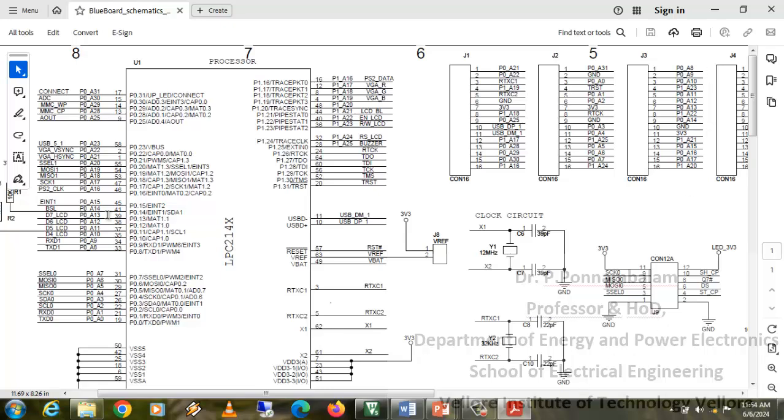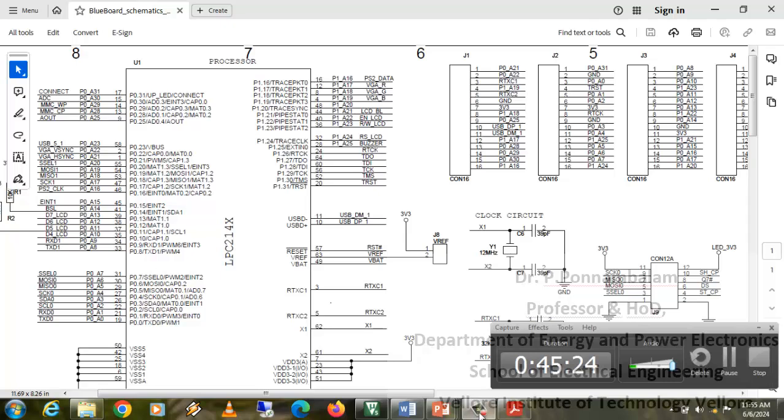So this is the way in which you can do the connection, while the 6th pin and 10th pin of this microcontroller should be connected to the 6th pin and 10th pin of your transmitting microcontroller for the I2C bus connection to happen. Let us see the hardware working.